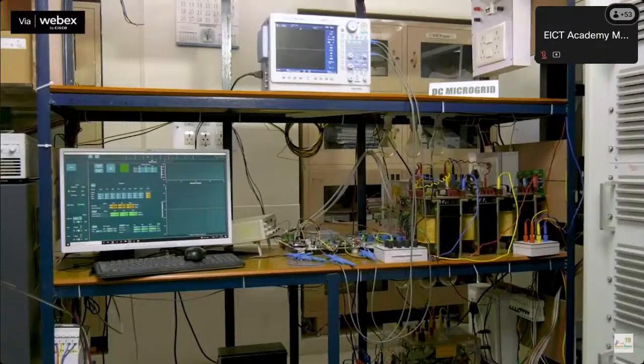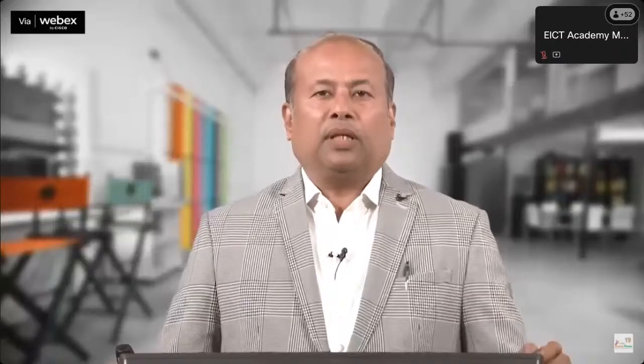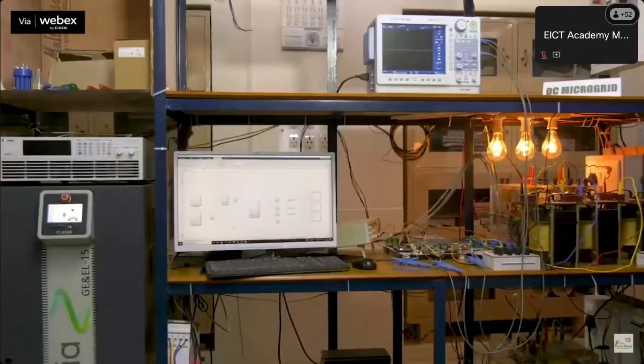At this MCB connection, bulb loads are connected in a parallel path and they act as a load. The other side of the MCB is connected to the output of the grid emulator, while the input side of the emulator is connected to the distribution system, which is connected to our campus network. Also notice that after the inductors, the wires are passed through the LEM current sensor. For voltage measurement, sensing is done near the MCB input and the sensed signals are connected to the LEM voltage sensor board.